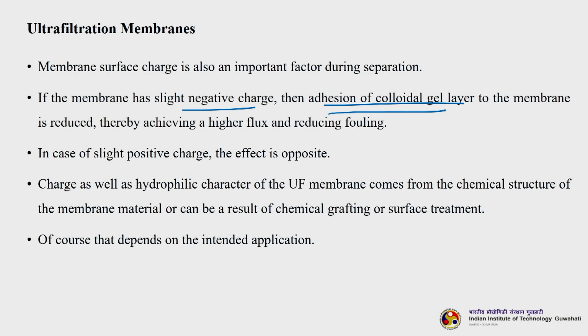That means that concentration polarization build up will be faster, and since it is a pressure driven process, some of these solutes will try to squeeze themselves inside the pores of the ultrafiltration membrane, thereby fouling the pores as well as the membrane. So, charge as well as hydrophilic character of the ultrafiltration membrane comes from the chemical structure of the membrane material and can be a result of chemical grafting or surface treatment. Of course, that depends on the intended application.